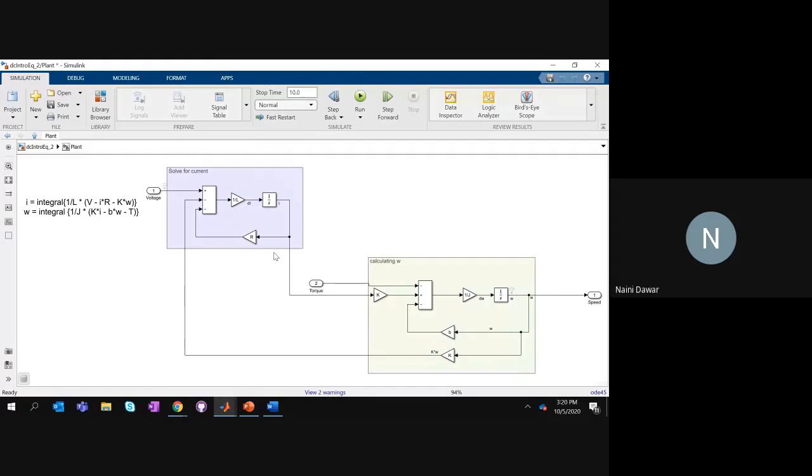If I want to see the impact of changing a parameter, I will go ahead and change the value of this resistance, or the inductance or any other parameter, and see the impact of that change on the output simulation. That is something we are doing manually, because this is the first principles approach. I'll show this in the power converters part as well, how you can change the parameters of your system and see the impact on the output. This is a manual approach.